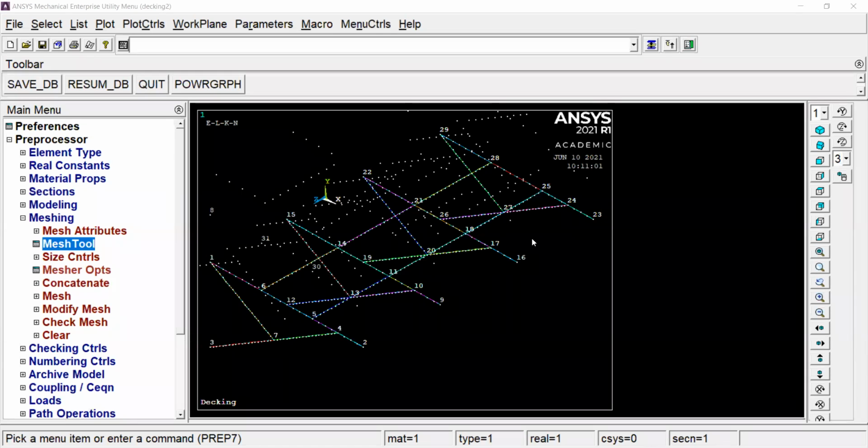So you guys doing bridges and billboards and all that, you have to bear that in mind. If there's a structure behind it, you have to make sure that your plate is connected to that structure and it's not just sitting in free space, or just connected at the far corners, because in reality, it's not connected at the far corners. It's supported by all the beams underneath.